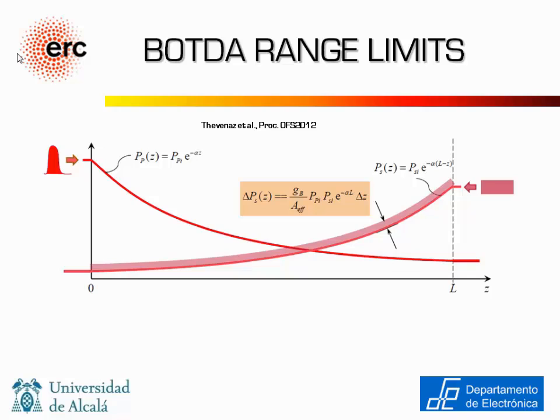So you send the pump pulse through one side, you send the probe pulse through the other side. And of course your response, as mentioned before by Luc, scales with this exponential decay. I want you to note that it decays with twice the attenuation of regular fibers. So it means that it is twice more challenging because you have two waves interacting.